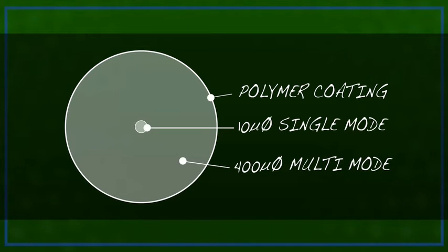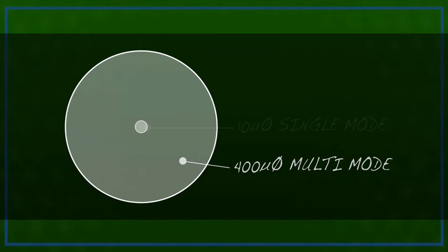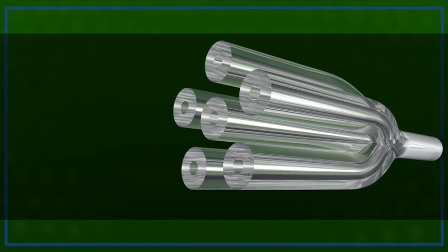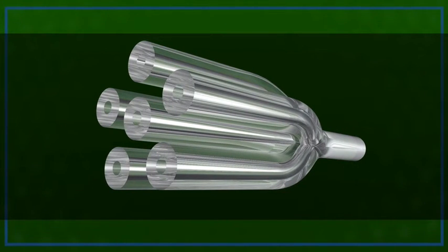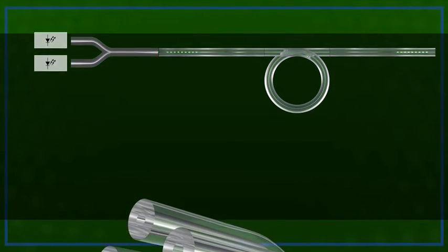However, the double-clad fiber is larger in diameter and has a second pump cladding with a very high numerical aperture. Now, even conserving brightness, this will allow a coupler with 6 legs at 0.22 numerical aperture each. Pumps of up to 600 watts per leg are commercially and competitively available for this coupler. This is encouraging.